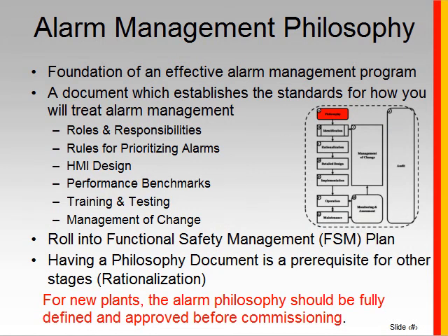Now, we don't start any alarm management plan without first talking about the need for an alarm management philosophy document. This is the overriding document that describes how a plant or site will execute alarm management, provides the rules and guidelines for how you will prioritize alarms, what is an alarm. It'll provide rules for how you design the HMI, your performance benchmarks.